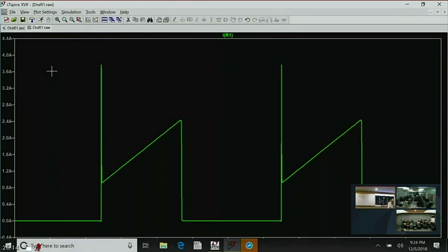And now in the 80s, what we would do is we would put an RC filter in front of the current sense amp, and you can imagine in your mind that at this point of operation, if you could pick a time constant where the resultant waveform might look something like this, it would come back down, you could still measure the peak current, and you'd still have enough bandwidth to make this thing kind of work. You could imagine that.